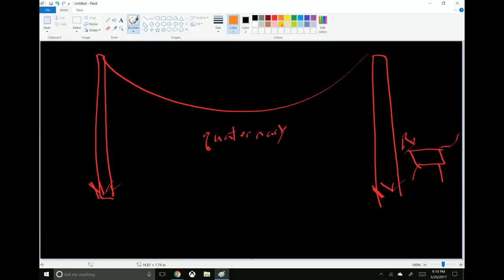Why doesn't it make a straight V, down to the bottom? Why doesn't it go straight across, then down, then over, then back up? The reason is that any deviation from the catenary curve will raise the potential energy. The catenary is the shape that minimizes potential energy. Any deviation from that will raise it. Even a little bit is bad. It has to minimize the potential energy, and that curve is how it does so.